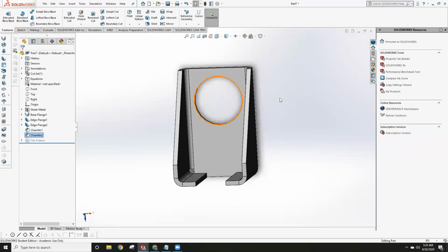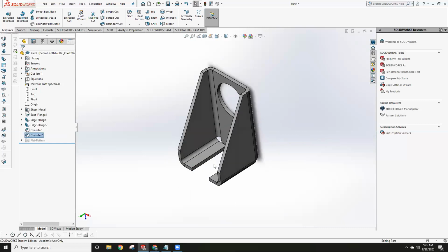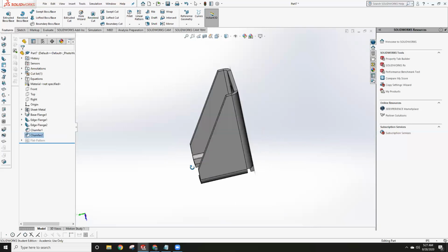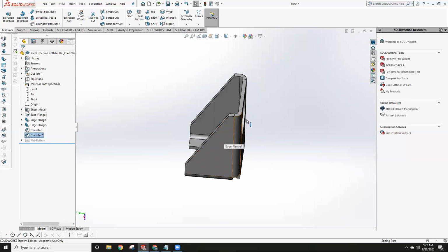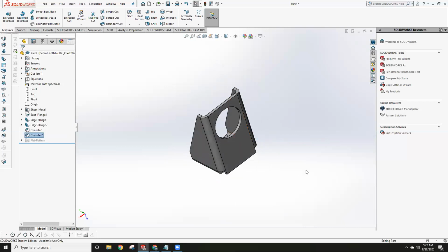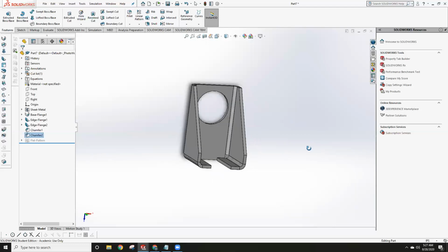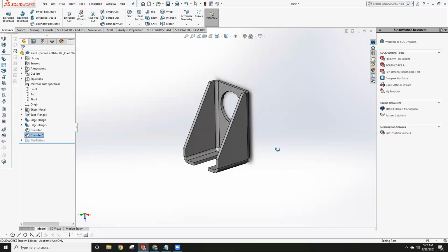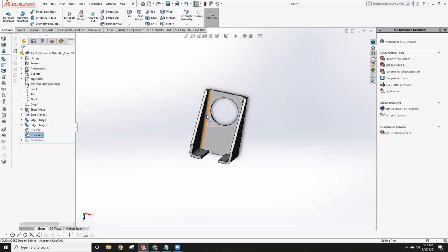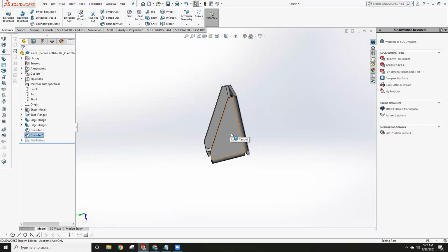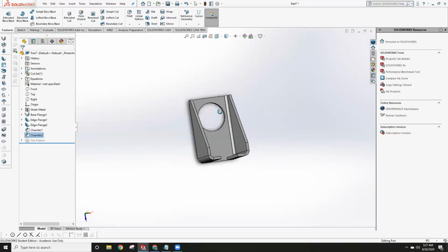But let's talk about why I did it like this. What this is supposed to be for is an intake would be mounted, the axle that the intake pivots on would be mounted to bearings that sit inside here. So why did I go for this design and not something simpler? That's sort of the whole thing with sheet metal. I mean, the simplest design would be to take a piece of 2x1, some VersaFrame, cut a big circle in it, stand it upright and put a gusset on it or something. I don't know. But since we're working with sheet metal, we can make these nice, pretty parts.